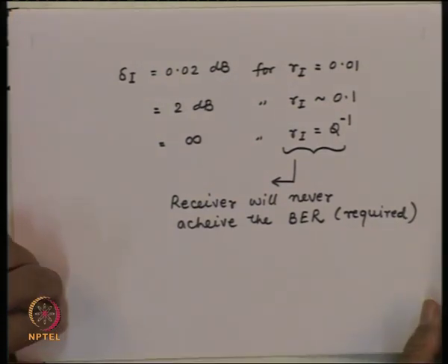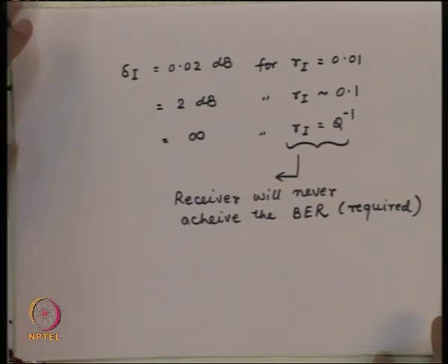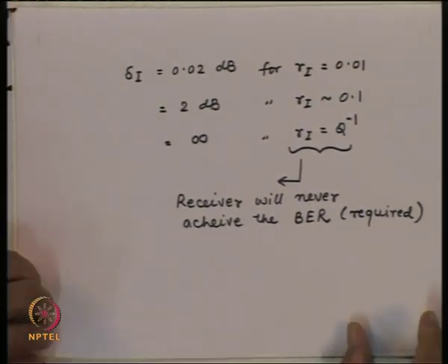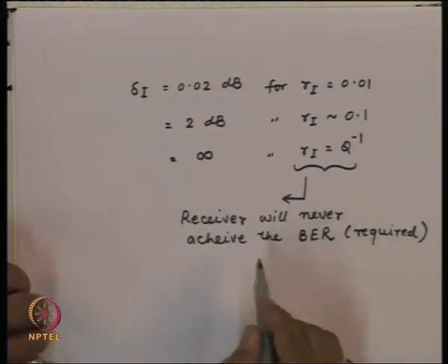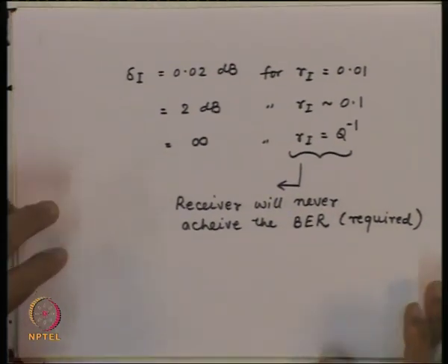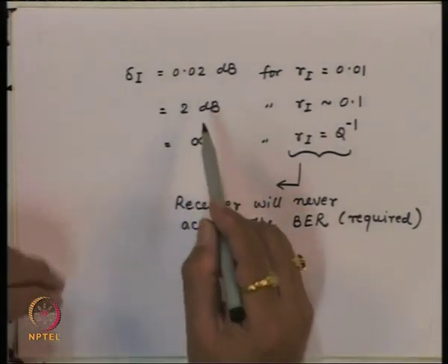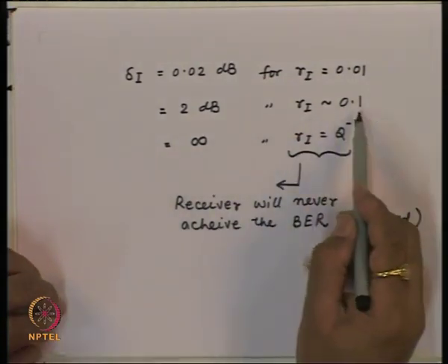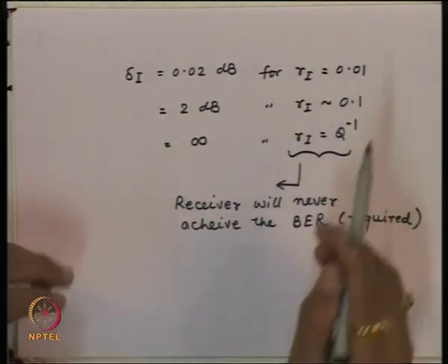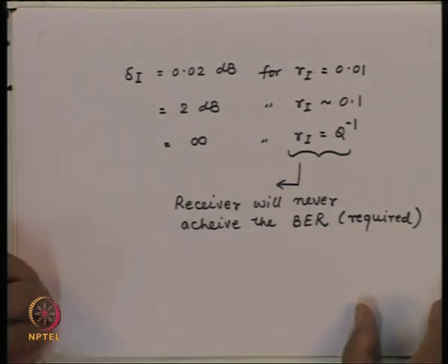So, that is the reason when we talk about the noises, especially this is going to come from the laser. So, this noise has to be kept low, so that the power penalty is again within the specified limit. Or in other words, if we say that maybe about a dB of power penalty is okay, then the relative intensity noise should remain of only few percent level. Otherwise, the power penalty will be excessively large.